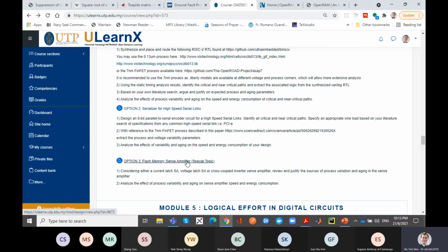Normally, in the old days when they created microprocessors, they would identify the critical part and design it by hand, to break it up so that they could speed up the microprocessor, because you have your max delay and your min delay constraint. Min delay sets the race time, max delay sets the maximum clock frequency. Max delay is the logic path that has the longest propagation delay in all your circuits. That sets the maximum clock frequency. So if on the critical path I can reduce the max delay, you can sell a chip with a higher clock frequency. And if I keep doing this for the critical path, then the next near critical path, the next, slowly I can bring my chip up to a higher frequency.